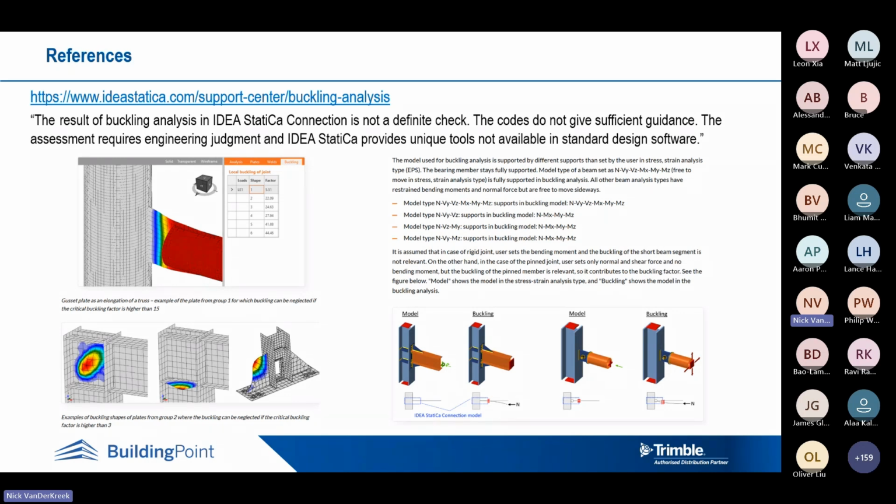We do have a very advanced and a very practical design tool here in IDEA StatiCa for daily use. Typical structural engineers can use this to make their strength checks, including a buckling analysis and so on. But at this point, as I say, it's not quite as clearly defined, and the software doesn't give a green tick or a red cross as a pass or fail. Maybe in the future it will, but for now we have to make a judgment about these things.